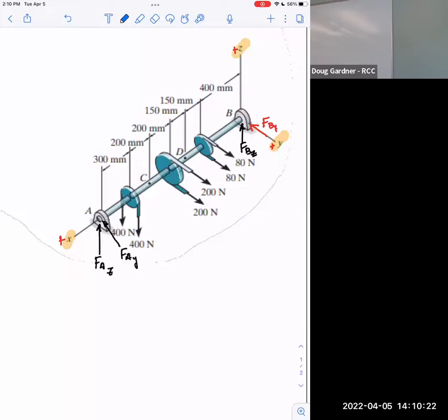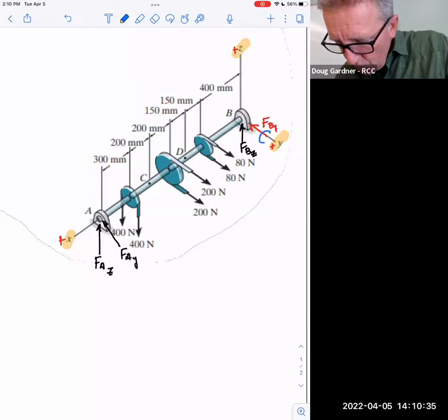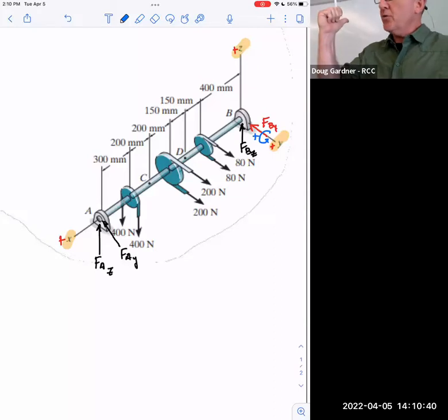Moment around the Z axis. Oh, no, that still gives you the moment around the Z axis. Because of the right hand rule, that is positive rotation. Again, your thumb goes toward the positive axis and your fingers point to positive rotation. You're tracking with that, okay? Now, again, the only reason we care is we have different forces trying to get it to rotate in different directions. And if we get those signs wrong, it's going to make us get it wrong.